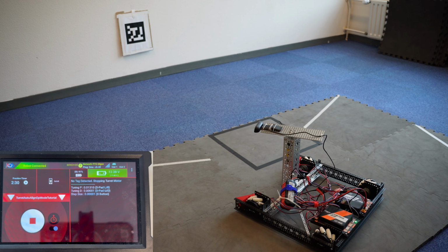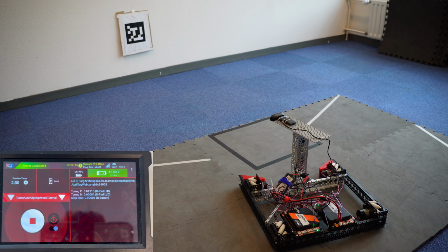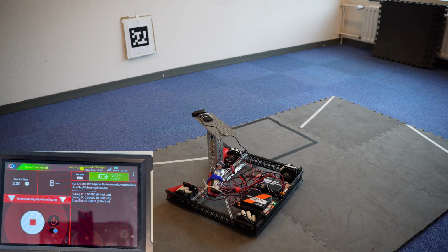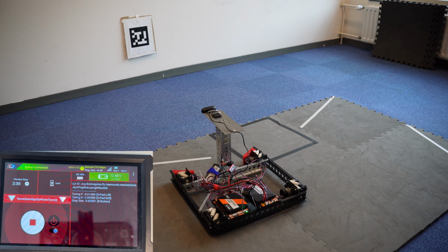So I might need to go back and change my step sizes, because I don't believe that I have the ability to do a step size any lower than 4 knots. So let's add in an additional step size here. Okay, I forgot to increase the size of my formatting for that step size to be able to show 7 different points, but I can't show 7 different points at the moment. So I have a D of 5 zeros and then a single 1 here. And this one's actually pretty solid to have a much lower D. So you need really low derivative.